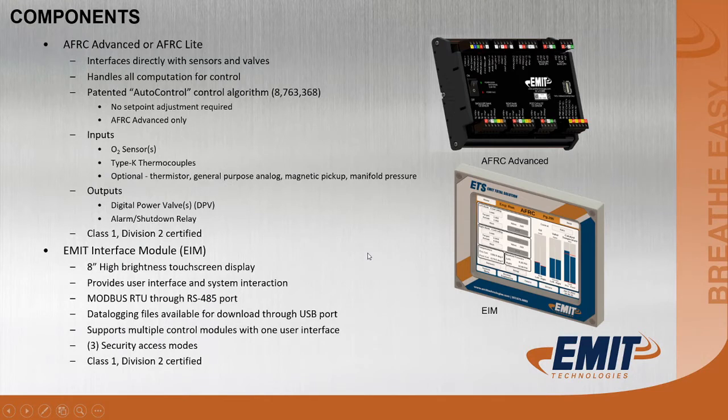The EIM, this is the display. It's an 8-inch touchscreen, providing the user with an interface and system interaction. It's Modbus RTU through an RS-485 port. Data logging files are able to be downloaded through the USB port. That's a great feature of this. We can handle up to 32 days of data, which is always being recorded. It's continually data logging all the inputs and all the outputs as well.